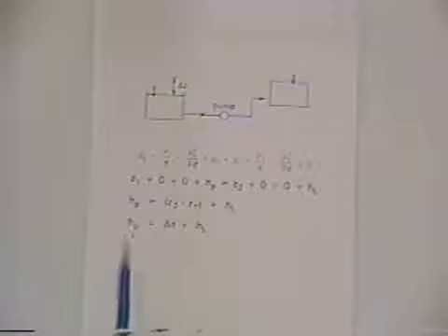And so here we're just looking at the pumping system. The pumping system is described by this relationship. And so if we go back to our example problem, the example says two reservoirs are connected by 850-foot long, 6-inch diameter pipe, and the friction factor from the Moody diagram is given, and a pump with the given characteristic curve is used to lift water from one reservoir to the other, determine the discharge rate.